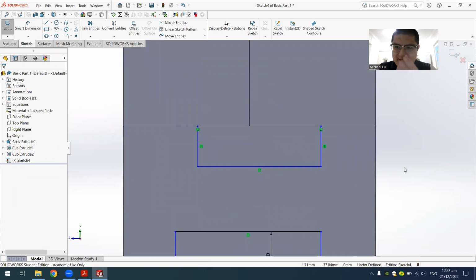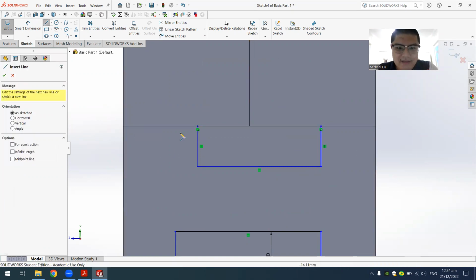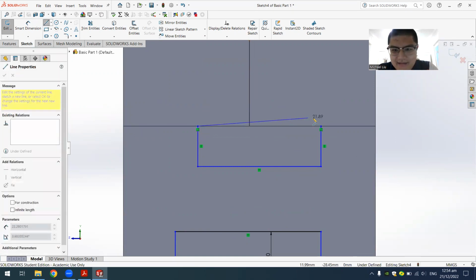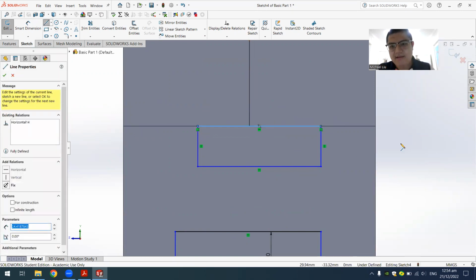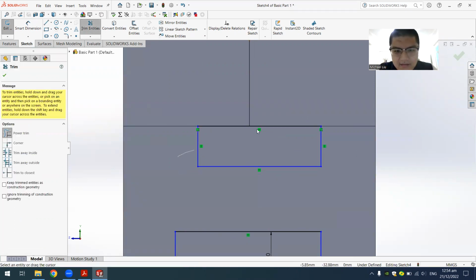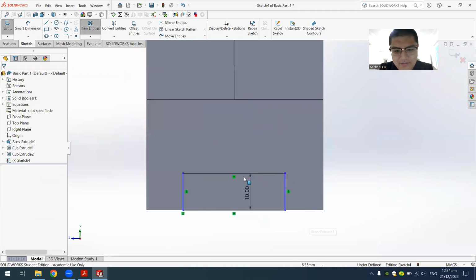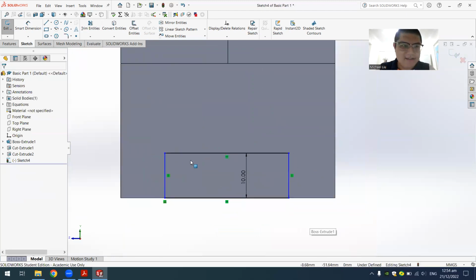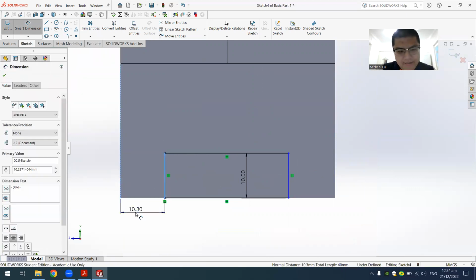Although it's a bit hard to see because the last side coincides with this line over here, this is still an open sketch. So what you need to do is manually add this last side, and this will become a closed sketch, and you can extrude it and add features to it. Of course, the easier way is just to draw it using a rectangle. Rectangle always has 4 sides. So I'll continue.